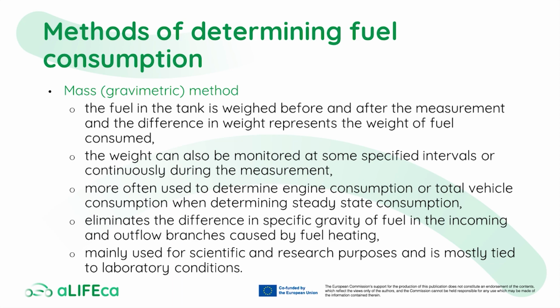The weight can also be monitored at some specified intervals or continuously during the measurement. This method is usually used to determine engine consumption or total vehicle consumption in a steady state. It eliminates the difference in specific weight of fuel in the incoming and outflow branches caused by fuel heating. Therefore, it's mainly used for scientific and research purposes, and it is adapted to laboratory conditions.